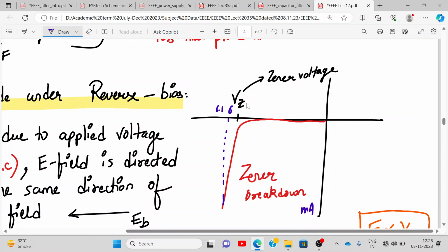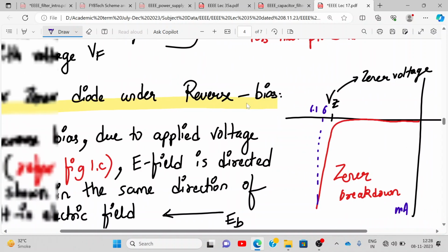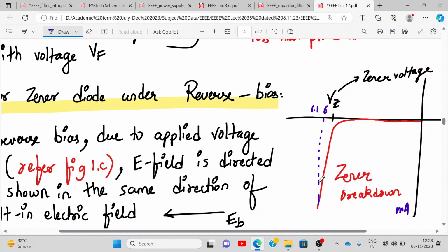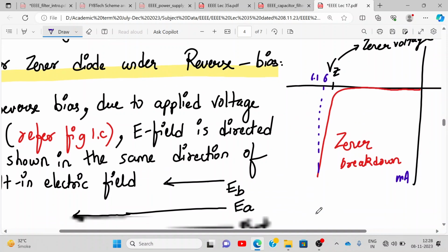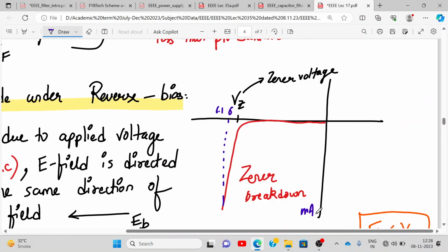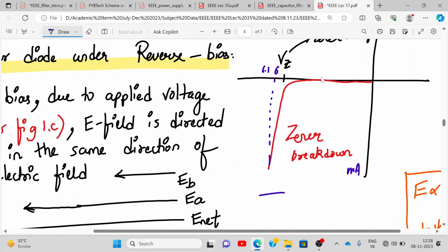So this is applicable in a voltage regulator, where we want the voltage not to change, while the current can change. So that's why the application of Zener diode is as a voltage regulator. There is hardly any change in the voltage, but you get a controlled current. So that's why for the Zener diode, can you see the symbol over here? This indicates current is flowing in both the directions, forward bias and reverse bias.